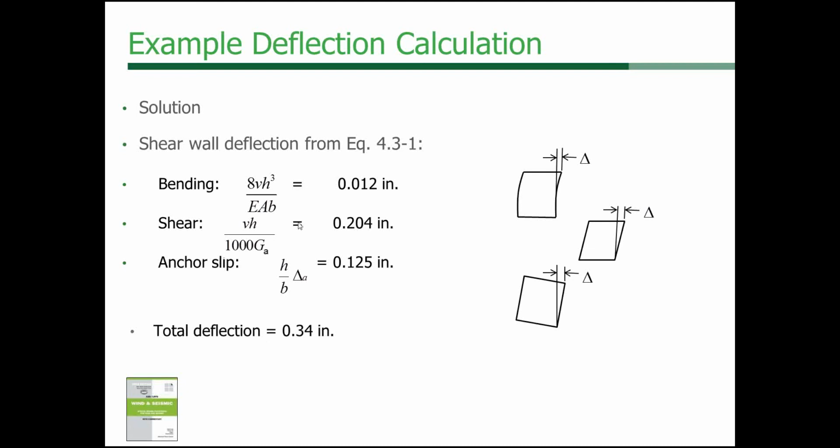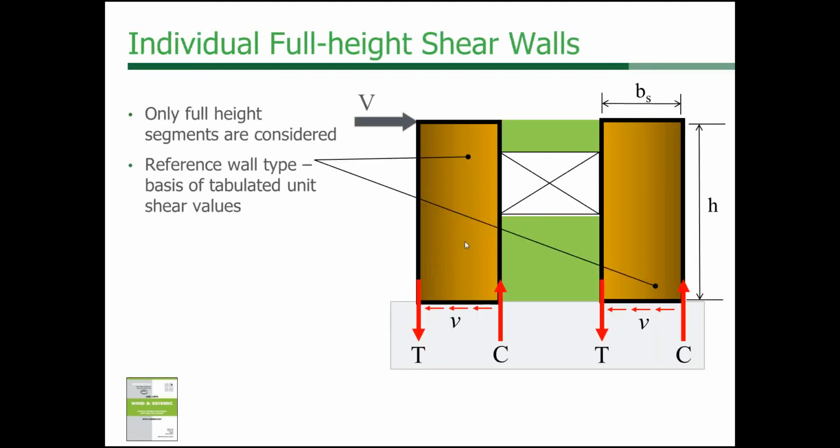The one thing I want to point out is that the biggest contribution to the equation is this middle term, your shear, all things being equal. That is where you can really build in some strength or performance into your shear wall, determining your wood structural panel and your nailing. I mentioned that in the beginning about what provides your strength and stiffness of a shear wall. So that contributes quite a bit to the overall drift of your shear wall.